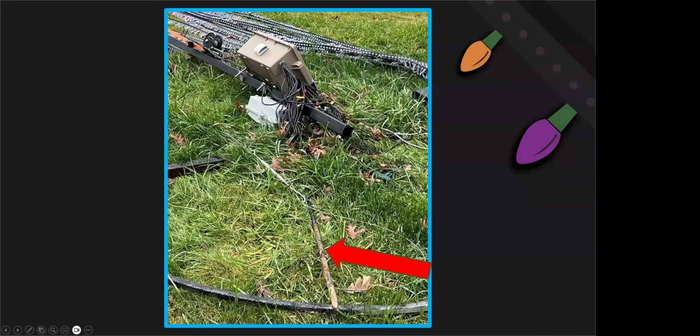If you have a failure of the connection point here at the bottom, that kicks out a little bit. But if your top was totally rigid, there would be nothing making it go side to side. It would stay in place. This might be a little bit offset, and a lot of the force is going to your guy wires, which would keep it where it needs to be, even though it was leaning a little bit. But you can see here, this just pulled out. You want to make sure those anchors are going to be able to take the weight of your tree if it tips.